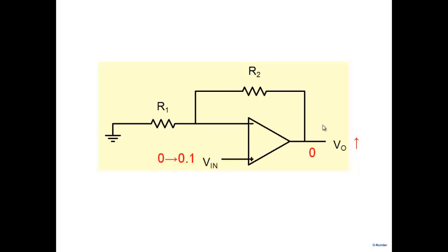As this voltage tries to increase, what will happen to this node? This is nothing but a voltage divider, so this node goes up. And what does this tend to do? It tends to decrease the voltage between them. And so up to what value can it rise? It will rise to a value such that this one becomes exactly equal to this, or very close to this, so that the op amp cannot raise it any further. So there's a negative feedback which is working, which will drive it to the required value.